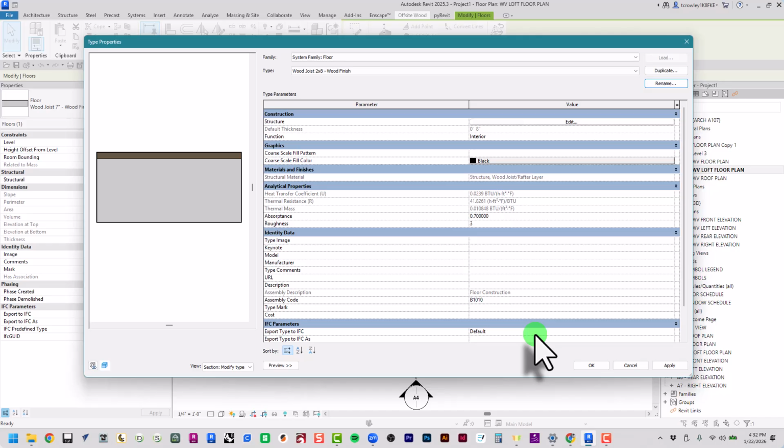But how do we know if we need 2x8s or 2x10s or 2x12s? So on our field trip, we learned a little bit about Roseanne King's tiny house. And one helpful tip she gave us was span tables, right? So as an architect, you can get a pretty general good understanding of what length you can have your framing be based on how much support you might not have under it. And that'll help you dictate how tall those members are, right?